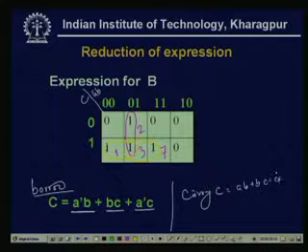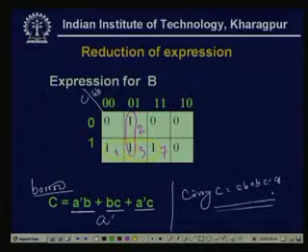So, again it was a sum of product and 3 AND gates are needed and one 3 input OR gate. Here also the same number of gates are needed, totally similar structure or similar expression, only here there is one complemented variable as the input, which is my A dash. There, no complemented variable exists. This is the only difference between the full adder and the full subtractor circuit.